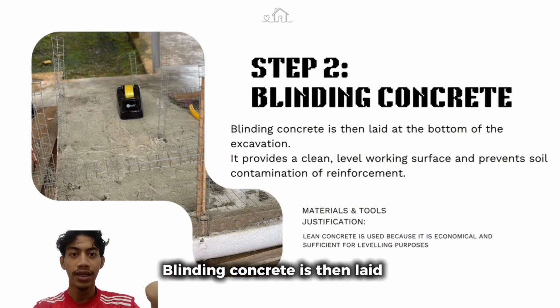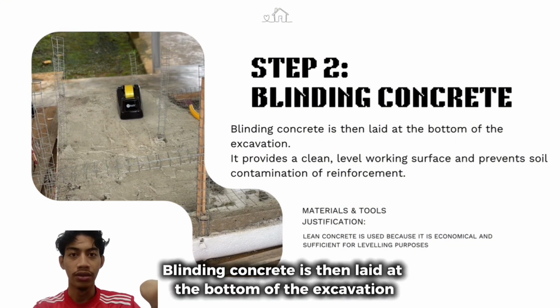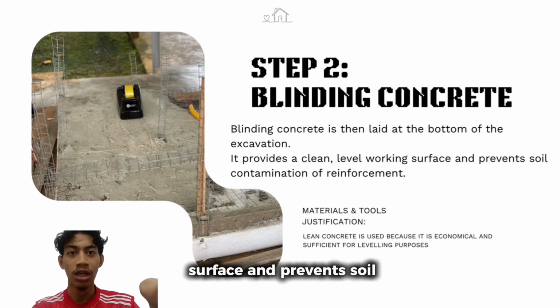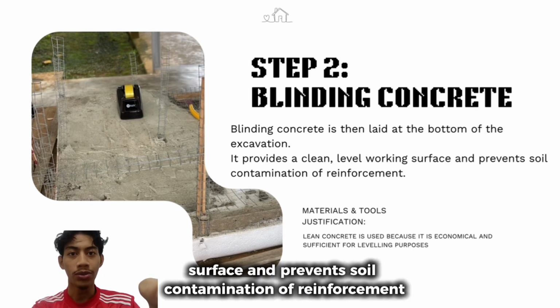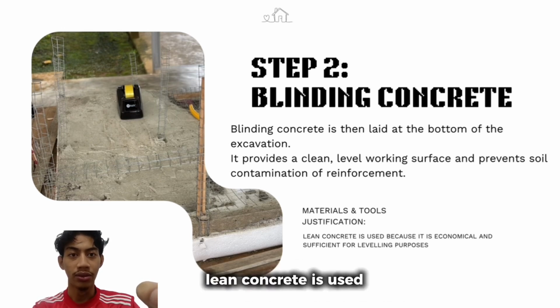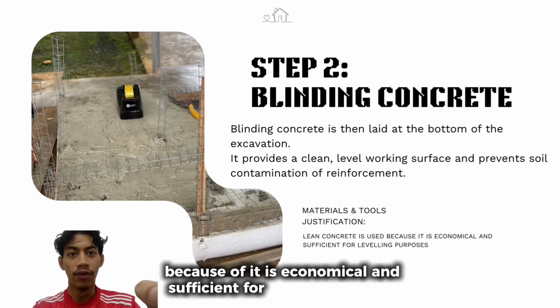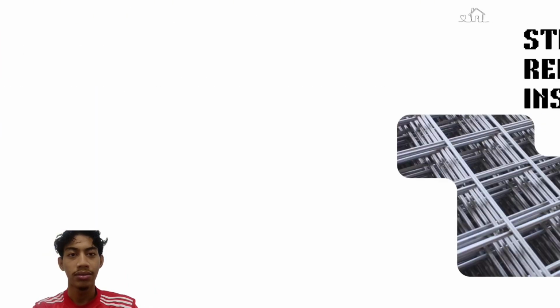Lean concrete is then laid at the bottom of the excavation. It provides a clean, level working surface and prevents soil contamination of the reinforcement. Lean concrete is used because it is economical and sufficient for leveling purposes.